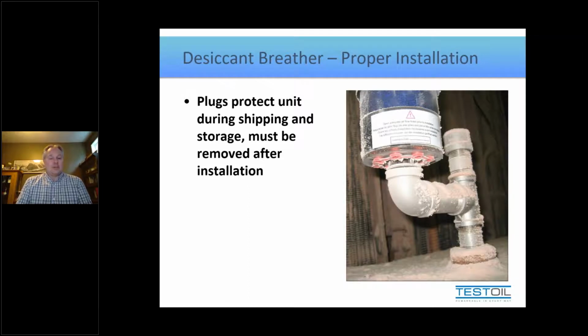There's no point trying to choke the flow of air into a breather. You just let it breathe as it wants to breathe. So with these things, like I said, you do have to take the right measures when you install them. Seal everywhere that isn't a point of entry that you don't want air going through. So fill caps, dipsticks, inspection covers, hatches, all of those count. Make sure the air is actually going through the breather. To do that, remove the shrink wrap, take the plugs out.